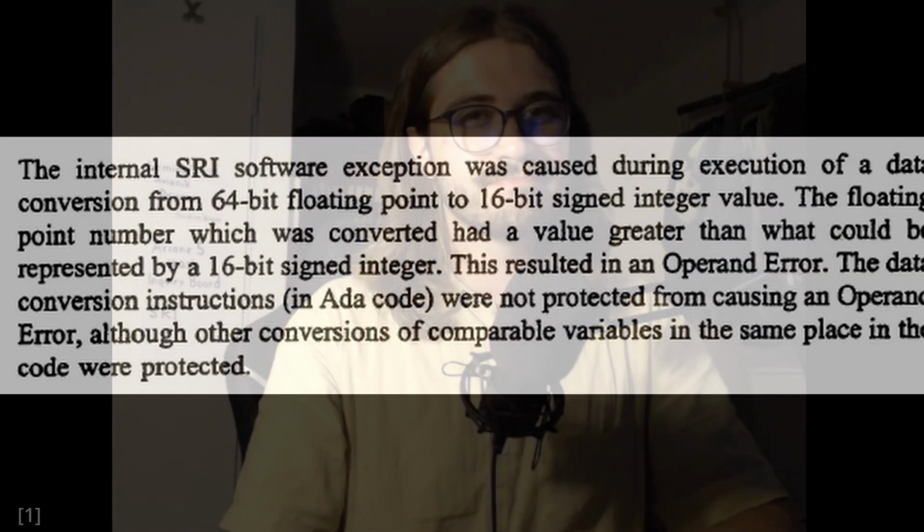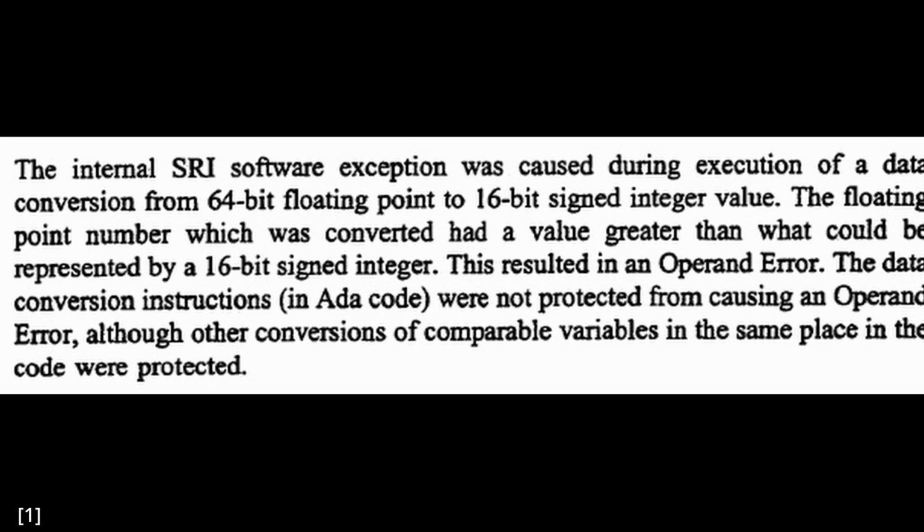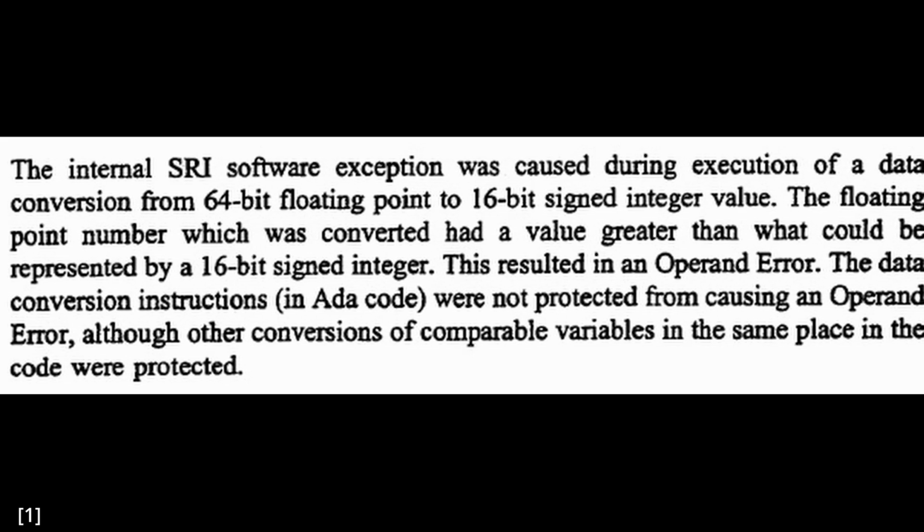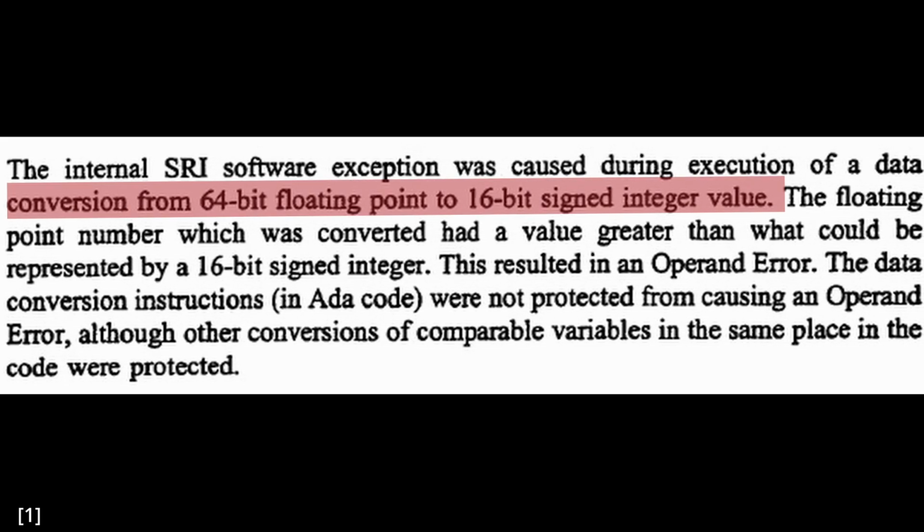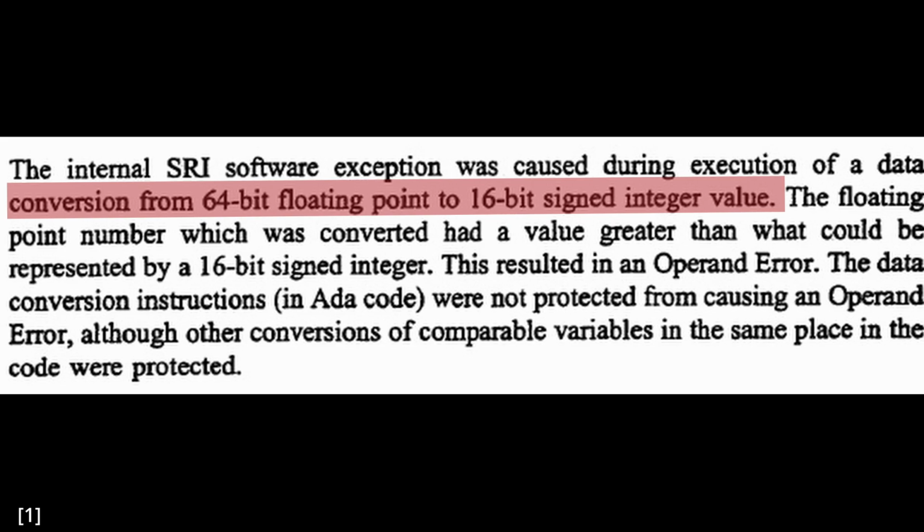So further on, the report also explains: The inertial SRI software exception was caused during the data conversion from 64-bit floating point to 16-bit signed integer value. Now the converted floating point value turned out to have a much bigger value than what could have been represented by the integer value, and this led to the operand error. So now let's focus on the SRI, because this is where the software bug comes from.